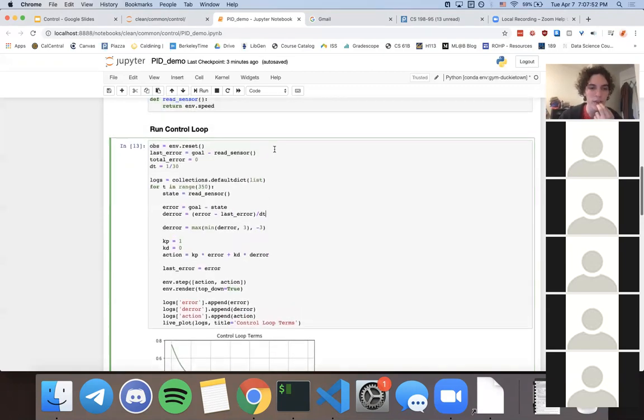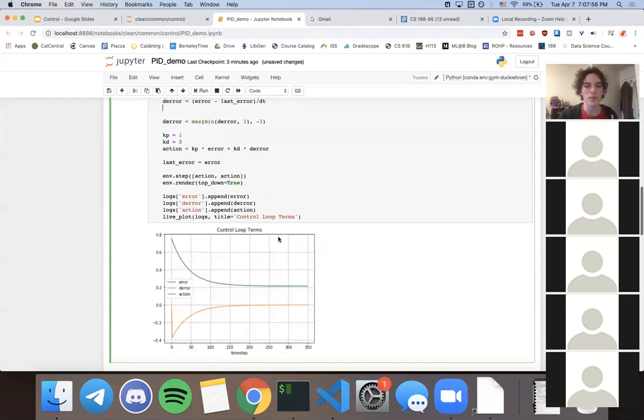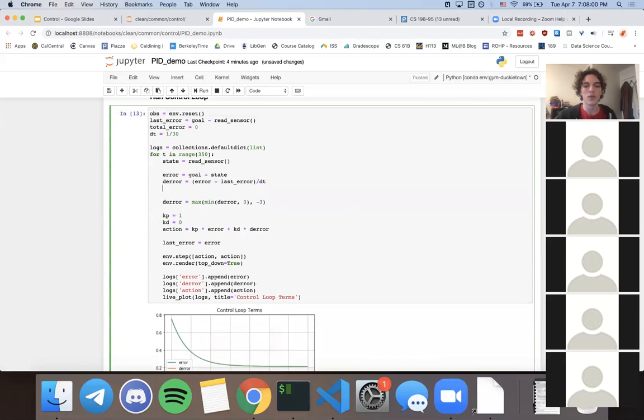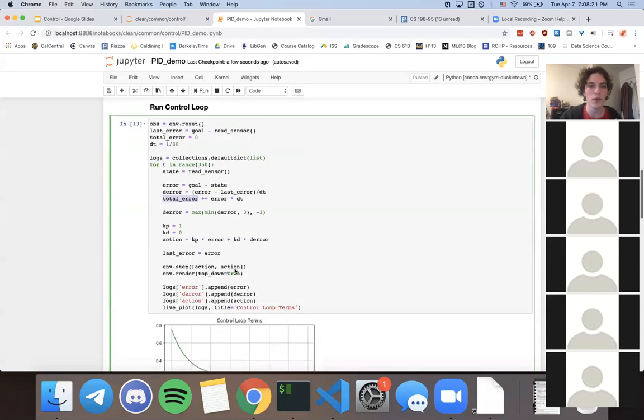Yeah, so our error is in V, and we just want to integrate that to get the integral of what the difference in velocities is. So at every time step, how do we do integrals? It's dt. We'll add the current error times dt. Okay, now we have a tally of an integral of this error in our velocity over time.